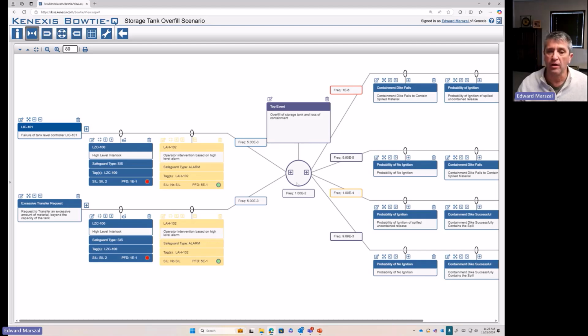So a failure of a protection layer that's used against multiple causes will aggregate very quickly, but its failure probability is not a function of how many causes it's associated with. It's this risk aggregation number where that shows up, the fact that it's so critical because it's used in so many places.